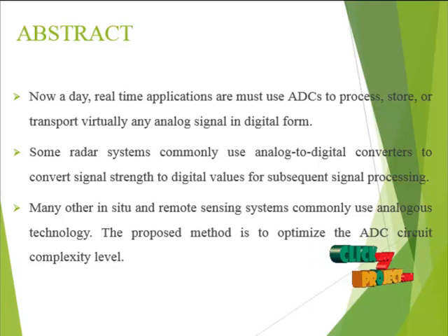In our process, mainly we focus on the pipelined ADC, which has been taken as the optimal architecture for multimedia applications that require fine resolution, low power and high speed. However, it has been less considered for ultra low power applications due to the bias current needed in the operational amplifiers.